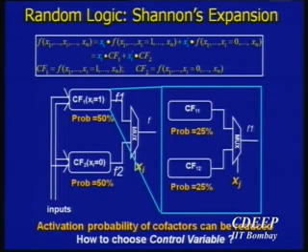You take the cofactor of that CF1 function and you break it up on literal x2. Now, how to select literals x1 and x2, I'm not going into the details of it. There are several heuristics that one can use so as to optimize the area of these functions, CF1, CF2, and so on. But the bottom line here is that now I have a methodology where I can activate certain sections of the logic based on the input conditions.